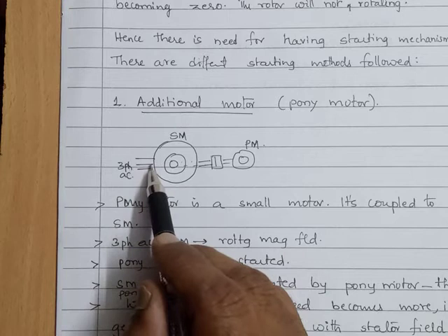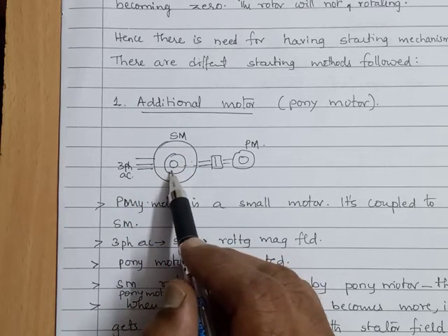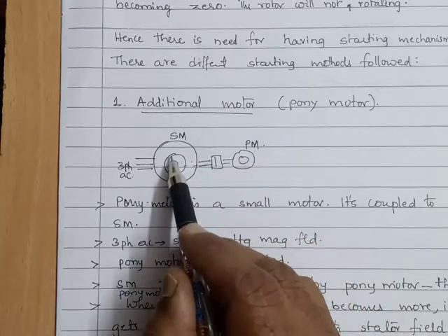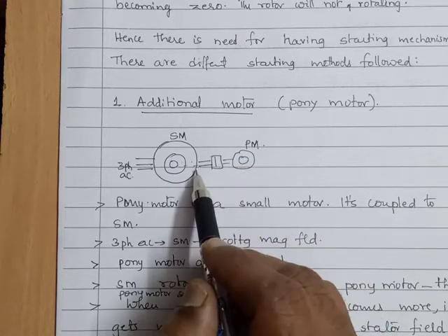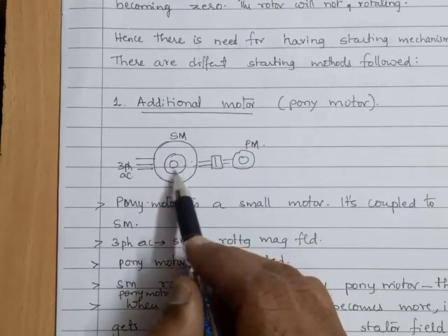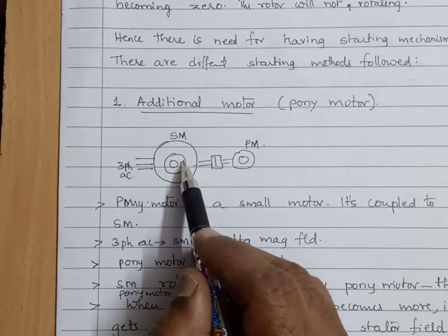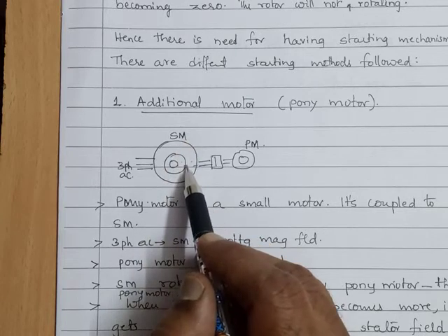Three-phase supply is given. Rotating magnetic field will be set up. The pony motor is started. It will rotate this rotor because of this mechanical coupling. When the rotor starts rotating, when it picks up the speed, when the speed is nearer to the synchronous speed,